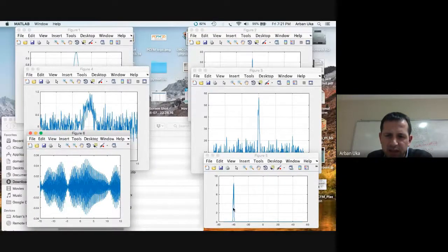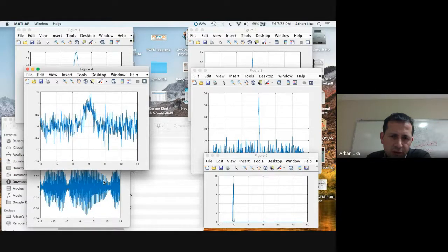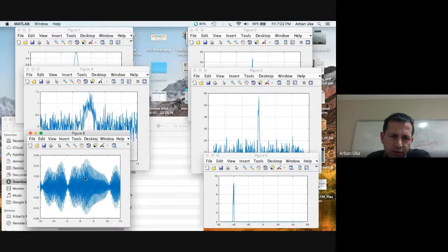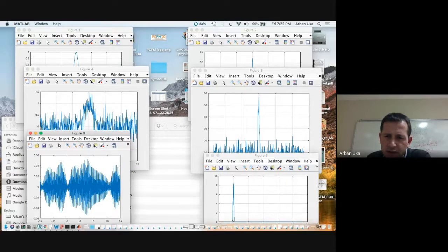which means that this specific frequency, which is located here at k equal to 40, is pretty narrow. If you see this one, this is pretty narrow. So we are keeping alive only this specific frequency. This is like a notch filter, and this is what we observe here. So in all of these locations, why is the amplitude a little higher here? Can we distinguish it? Can we figure this out? Probably not. Because around 0 we have high, and we have a very nice feature which looks like this.